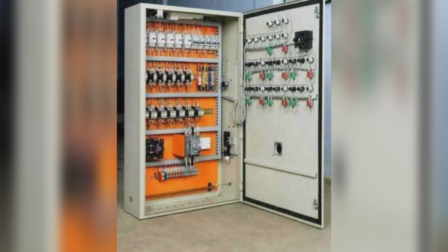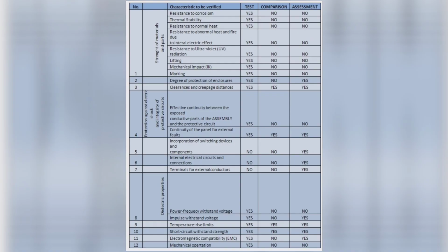Each enclosure will have an electrical safety rating designated by UL. UL means Underwriters Laboratories, which governs electrical safety. We'll also have an IP rating or NEMA classification, which designates the enclosure for indoor and outdoor application, waterproof or water resistant, suitable for hazardous conditions, dust proof, and explosion proof. Now, let's go inside the enclosure and talk about the components that make up the electrical control panel.